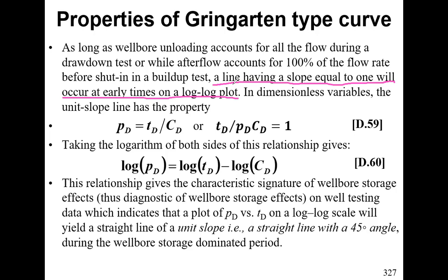If you take the logarithm of both sides, you have that the log of dimensionless pressure is equal to the log of dimensionless time minus the log of dimensionless wellbore storage.